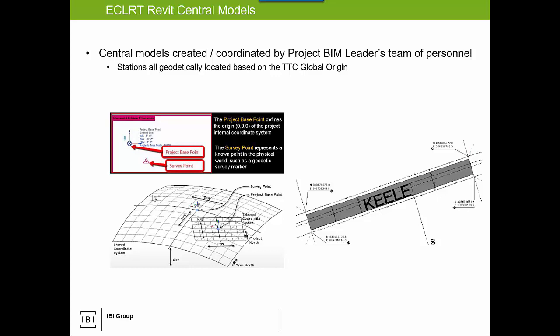So again, the BIM workflows, the application of BIM, catered and restricted, if you will, by the limitations of Revit. Keep that in mind when you're geolocating your Revit models, your shared coordinates, publishing and pulling coordinates. Are you dealing with a MicroStation deliverable like we were here? And because of that fact, we couldn't publish shared coordinates. Therefore, we had to build a proper workflow to accommodate. And that's what we had here.